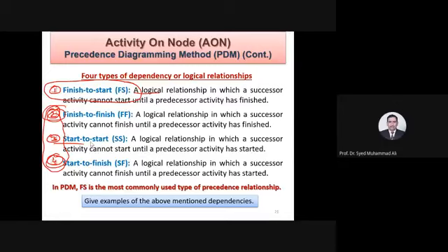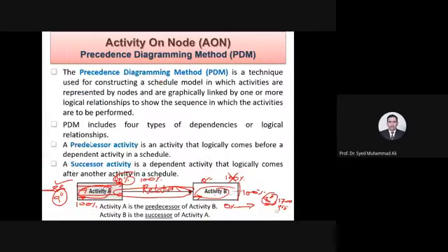اچھا پھر اس میں ایک اور چیز بتاؤں، سافٹ ویئر میں ایک آپشن یہ بھی ہوتی ہے، یہ میں نے ایم ایس پروجیکٹ کو زیادہ اگریسولی یوز کیا اور یقیناً پرائماویرا میں بھی ہوگی. آپ ریلیشن شپ ڈیفائن کرتے کیسے ہیں کہ آپ ماؤس کو لے کے اس لائن کے اوپر ڈبل کلک کرتے ہیں ان دا سافٹ ویئر. میں ایم ایس پروجیکٹ کی بات کر رہا ہوں اور پرائماویرا میں بھی کچھ اس طرح کی کوئی ہوگا پروسیجر.